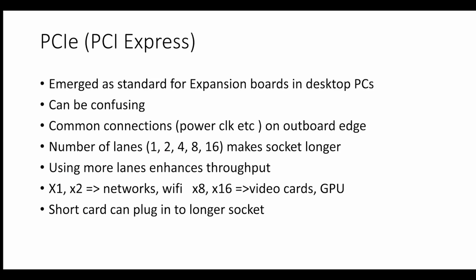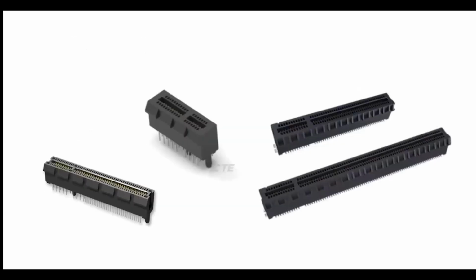Right, I'm going to nip onto the next picture and come back. There's a handful of PCI sockets. These are actually from the Radio Spares and Farnell catalogues and places like that for buying the sockets for repairing computers. But you'll notice that to the left of every one of those sockets is a little area of 22 pins. And then there's a key, and then there's the rest of the socket. And the rest of the socket is of variable length. There's one of them there that's got less than 22 pins. And there's one there that's got about 180 pins. Right? Those are all PCIe sockets.